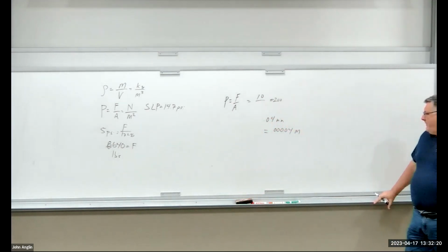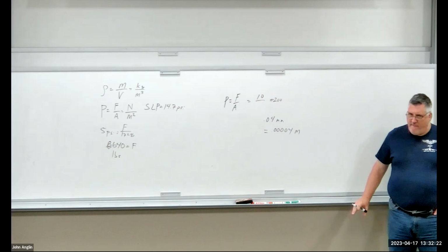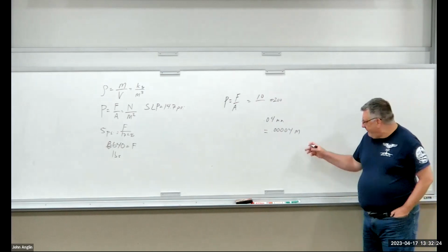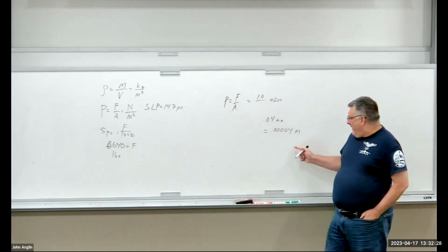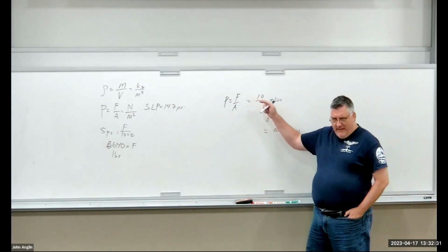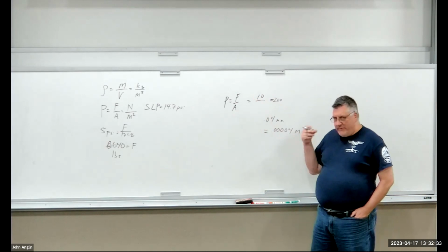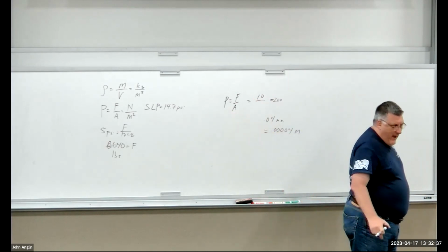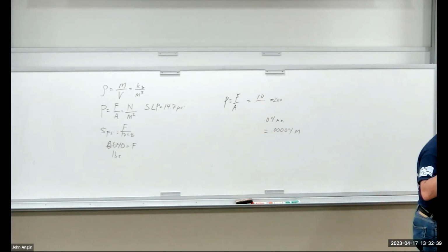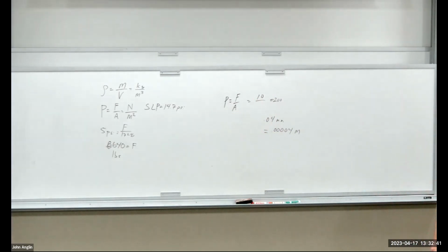So that's 0.00004 meters. If we square this, stick it in our area, you can see that even with just 10 newtons of force, the pressure goes way, way high. That's why the needle can penetrate your skin.